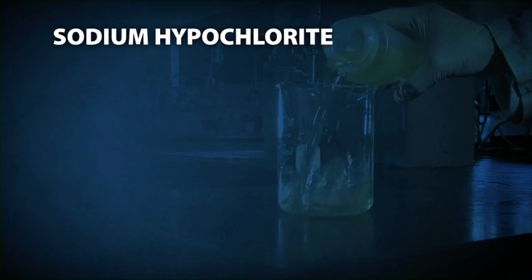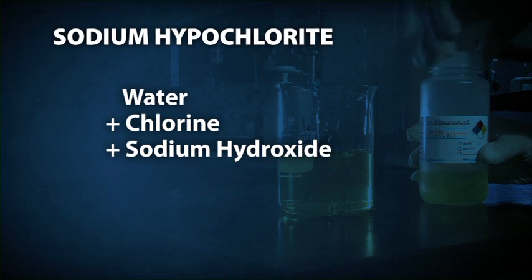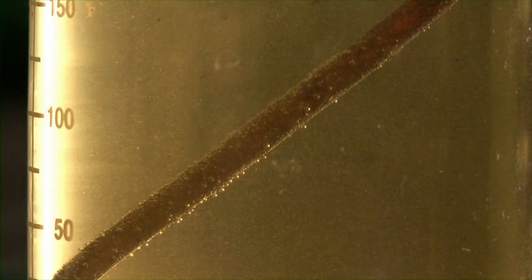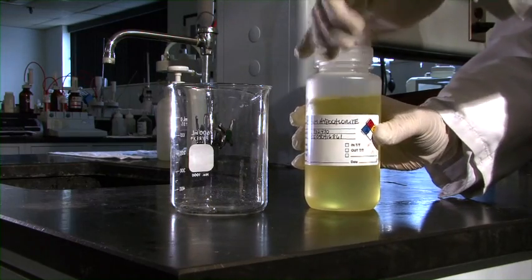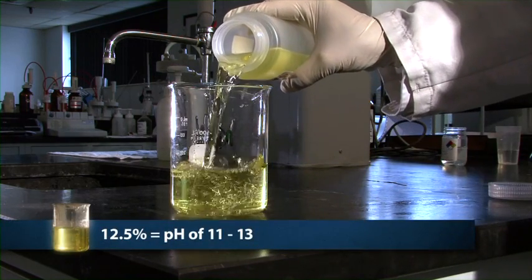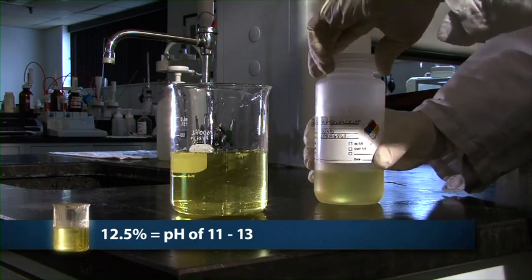Sodium hypochlorite is manufactured by combining water, chlorine, and dilute caustic soda, sodium hydroxide, under tightly controlled conditions. Sodium hypochlorite solutions can be corrosive. They can corrode a number of metals and other materials. The pH of sodium hypochlorite solutions will vary depending on the amount of free sodium hydroxide present. An industrial-strength 12.5% solution, for example, can have a pH ranging from 11 to 13.